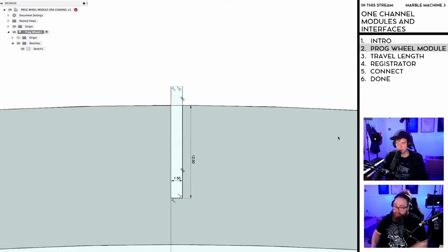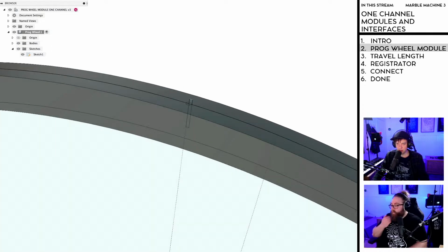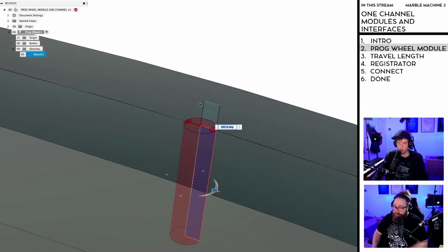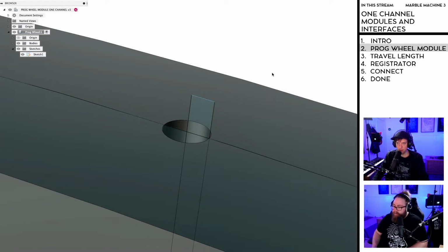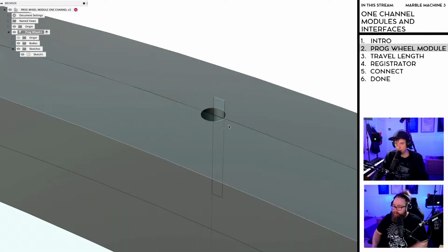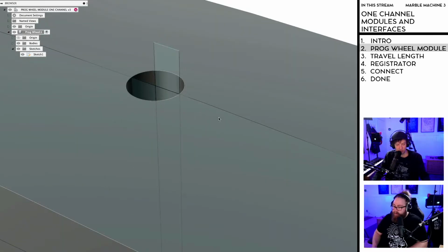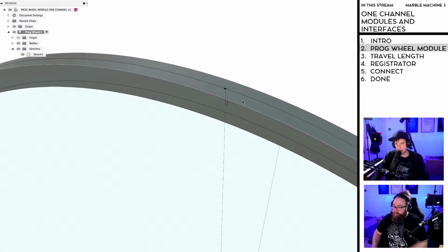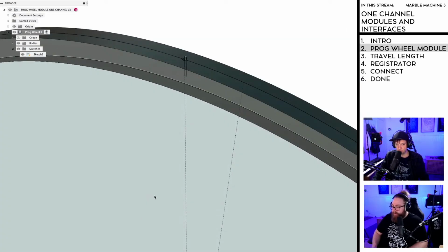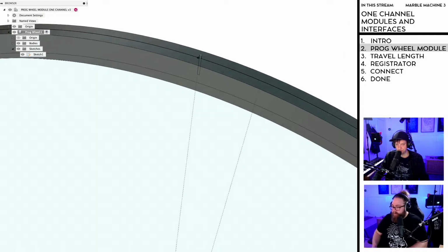So I'm going to edit this revolve feature and choose this as well. And then you see the hole looks much better, because it was just on the same surface, and we can't have that. And then I can do the same for the second hole.